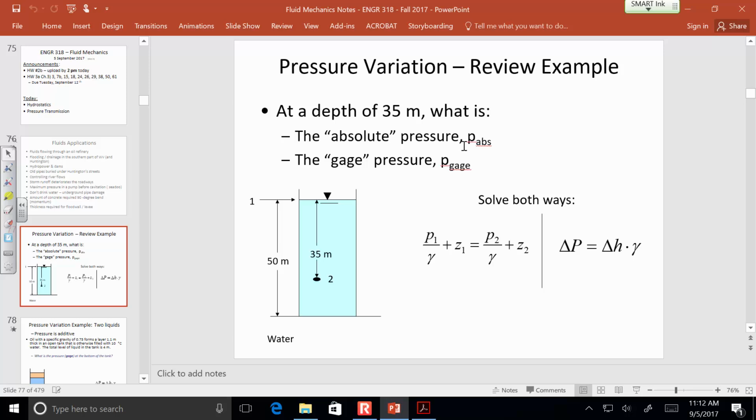So it's the pressure relative to itself. Gauge pressure means we're using atmospheric pressure as the starting point. It's the datum above which you'd measure any additional pressure. So here at 1, the gauge pressure is 0 because where the water is touching the air, they have the same pressure. When two fluids are in physical contact with each other at the same elevation, then they have the same pressure. And so the water pressure at 1 is equal to the air pressure at 1.